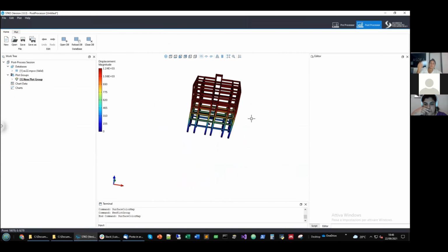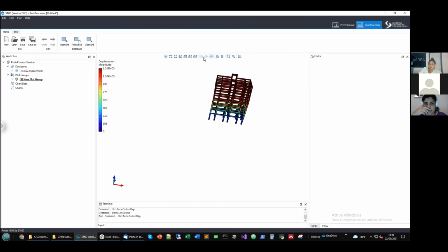Of course, you say I'm controlling the displacement of this, so I'm pushing this point forward, and this point will move to the target that I gave. So how can other points move more? I mean, if places detach, they would just move more or in a direction. So the fact that you pick a specific control node does not change the way the other nodes will behave unless you have, as in this case, rigid diaphragms. So all the nodes in each plane move the same.